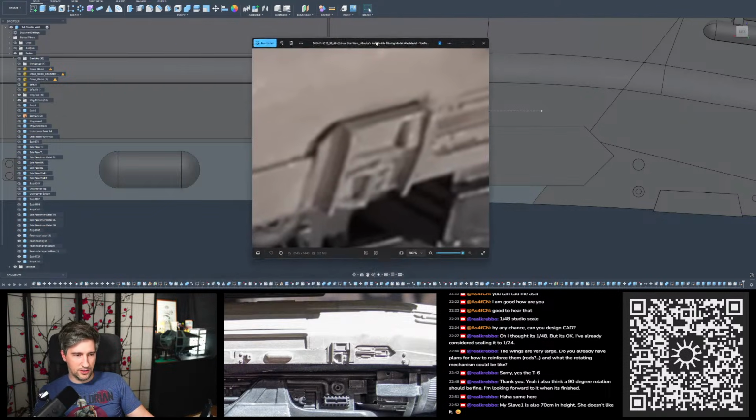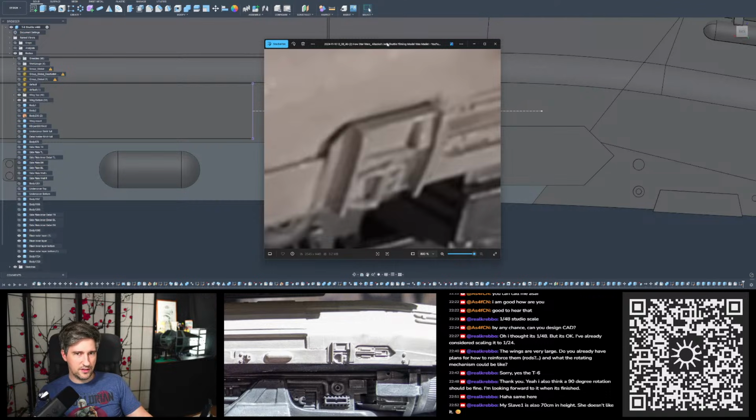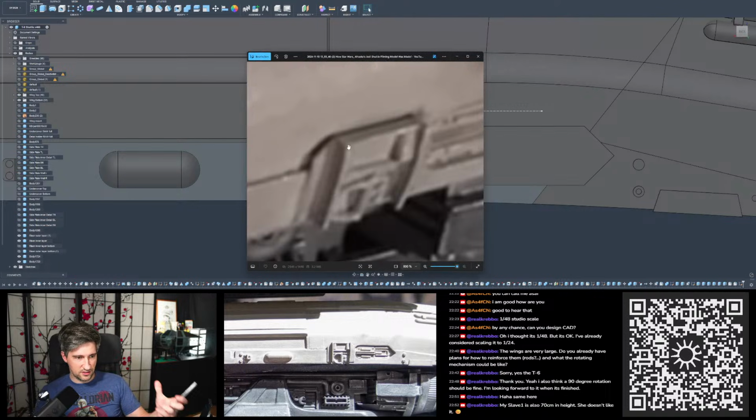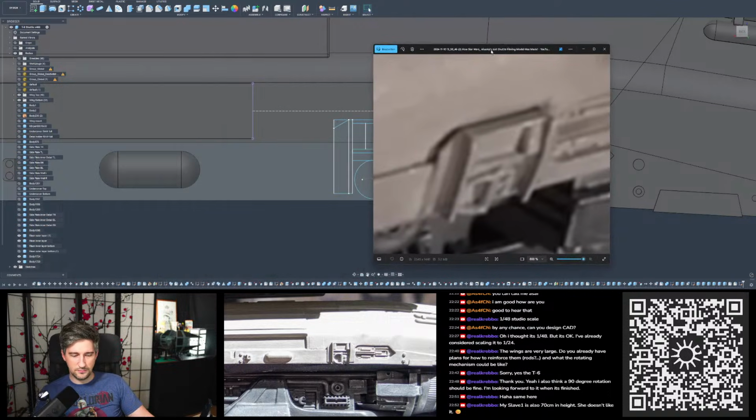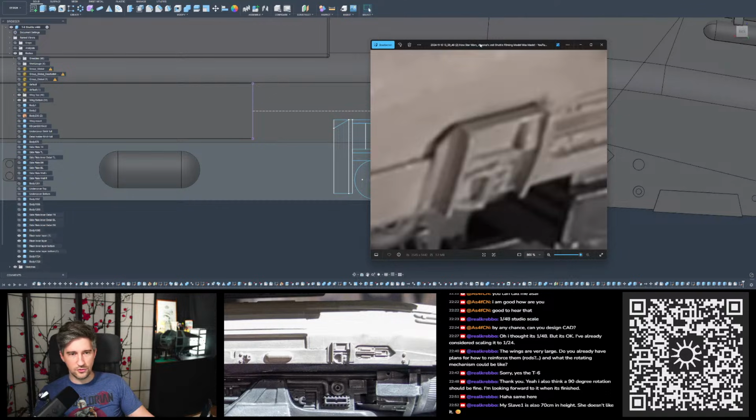I don't know if I should also leave that gap in the design, or if I should just extrude it towards this gap as well. Closing the gap would be better for printability. Leaving the gap, trickier to print maybe. You could break it if you accidentally touch it in the wrong way, but it's more accurate. What to do? What to do? I'm not sure at the moment.